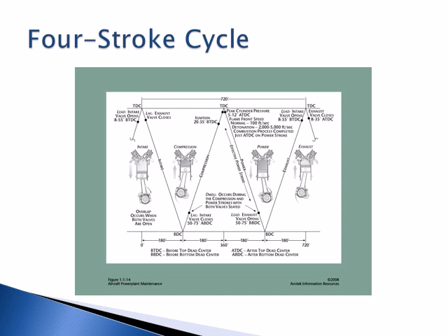The exhaust stroke follows, with the exhaust valve opening before bottom dead center and closing after top dead center, efficiently expelling combustion gases. Note the valve overlap at the end of the exhaust stroke and the beginning of the intake stroke, a key feature for enhancing engine breathing and efficiency.